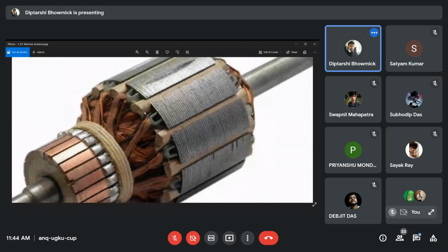Okay. If you look at the picture very carefully, you can see that in between two slots, there are the windings. We can see the brown part over here. But in this slot gap, the brown windings are not visible. What is visible is basically a wooden thing, isn't it? From the color and the texture, you can tell that it's something made of wood or something like that. Yes, sir. It looks like wood. Yeah. So that is basically the wedge.